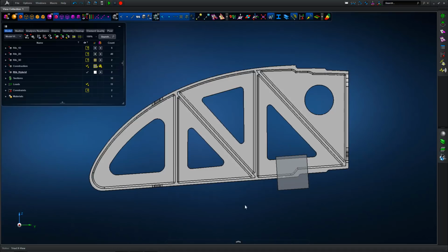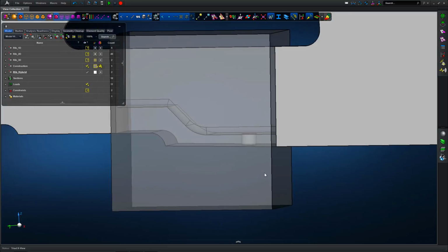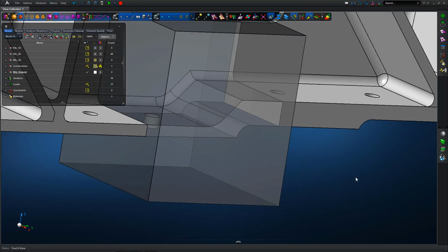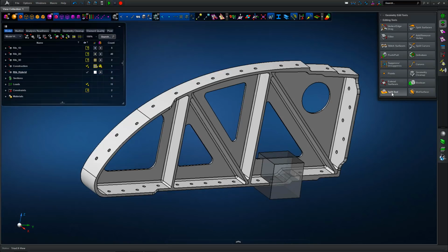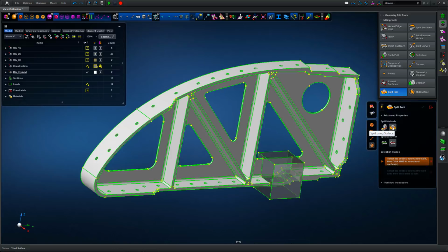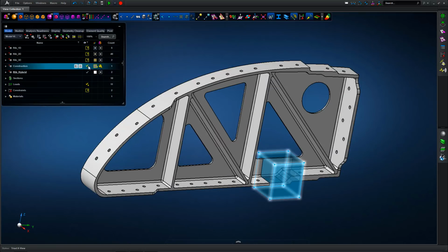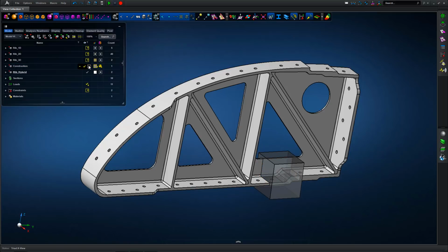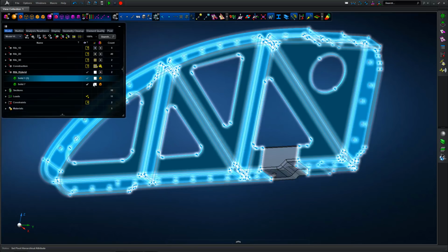So moving on to the final rib definition. So this is looking at hybrid modeling or meshing techniques. So rather than partitioning the rib in a manner that we looked at in the tetrahedral mesh example, what we're going to do now is physically break out a portion of the rib structure, again at a region of interest, and we can use different modelling or different meshing techniques for the broken out portion based on the underlying geometry.